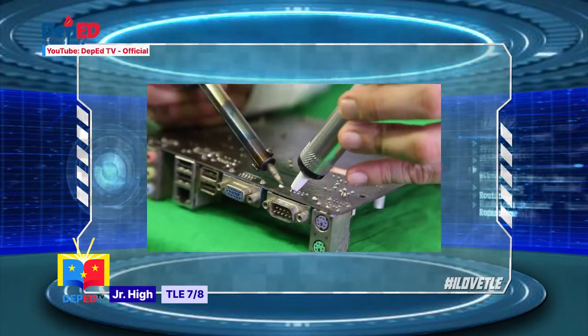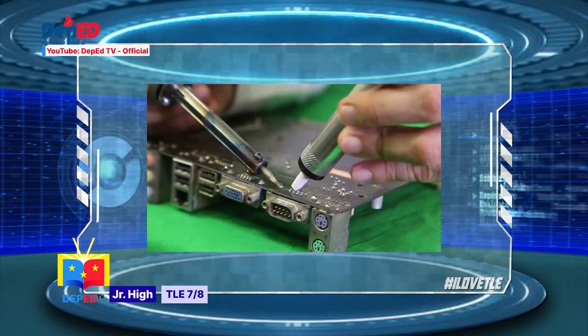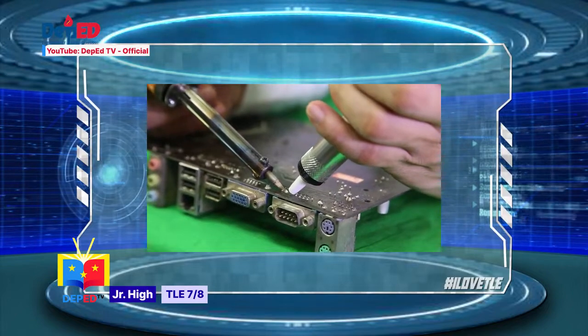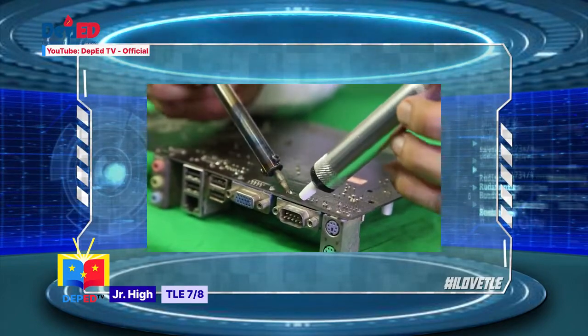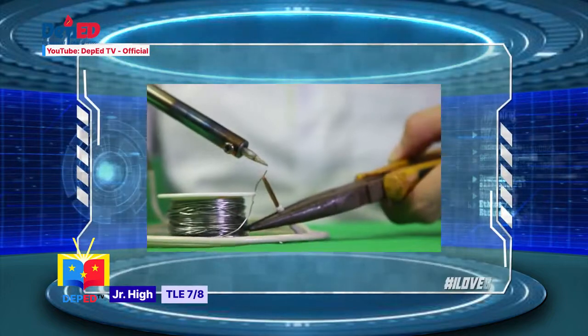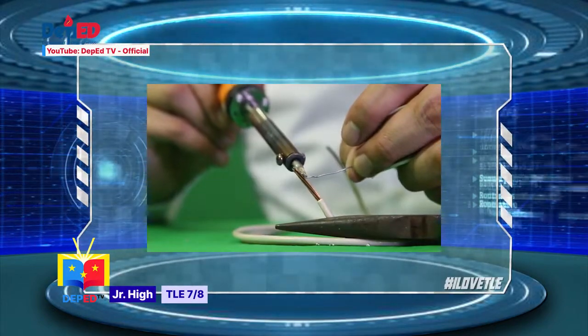Why? A solder will not take effect on dirty, greasy, and oxidized surfaces. Connections to be soldered should be cleaned just before the actual soldering operation. Items to be soldered should normally be tinned before making a mechanical connection. Tinning is the coating of the material to be soldered with a light coat of solder.